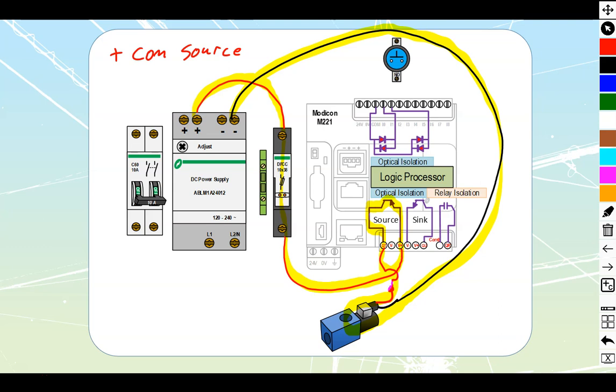Do note as well that if there was a ground fault off of this cable, it wouldn't make any difference, because at very worst, it would be able to track back to this supply if it were grounded. If we had a ground fault on this cable right over here, with a grounded supply, it would trip out this breaker, and it's not going to operate any loads outside of the field. It's a safe type of connection that we would be dealing with. Let's erase it.